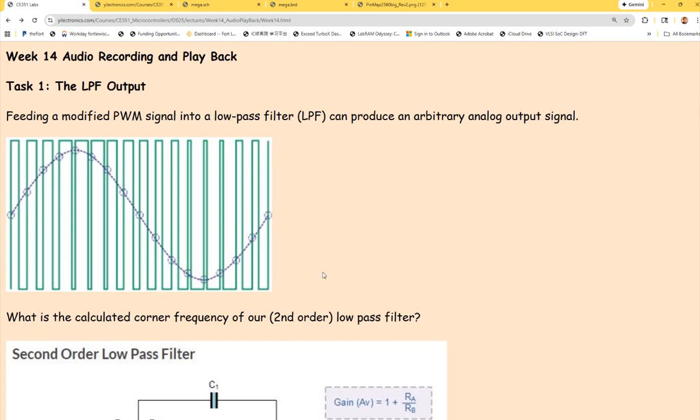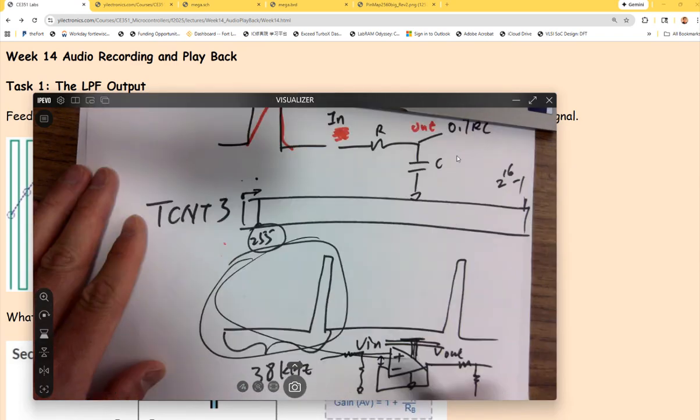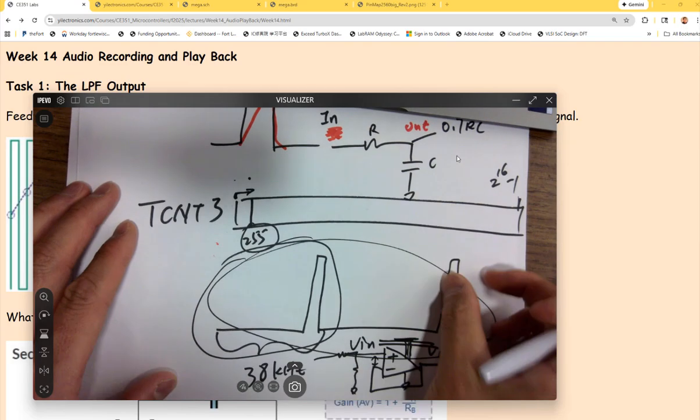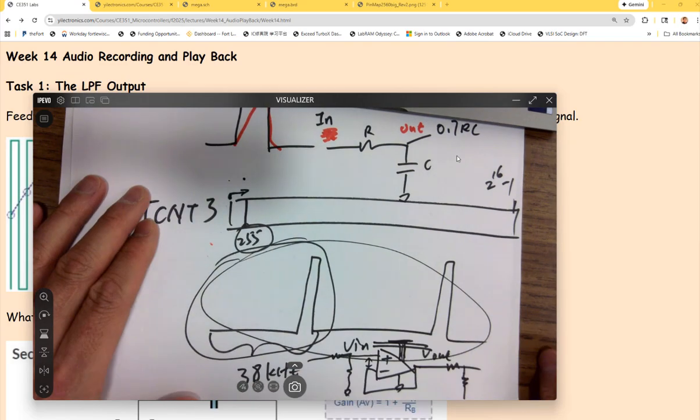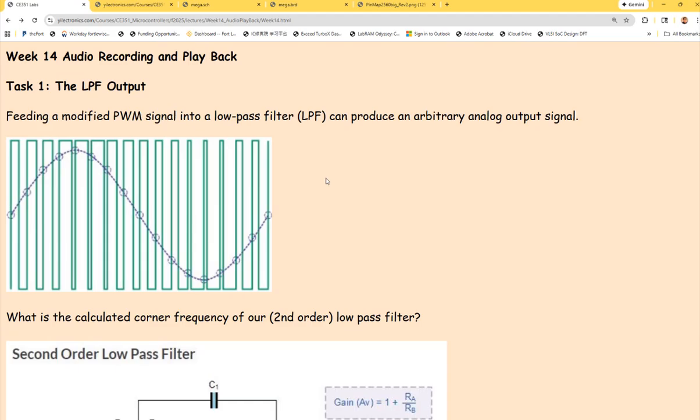So every time I press the key over there, I'm just getting a certain frequency of the PWM. It's either this or a wider one. It's a constant output. It's not changing. But in order to create something like this, OCR3N, OCR3A need to be overwritten in real time.